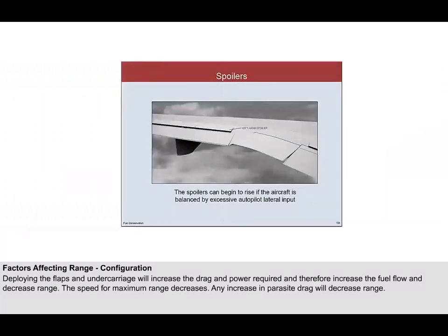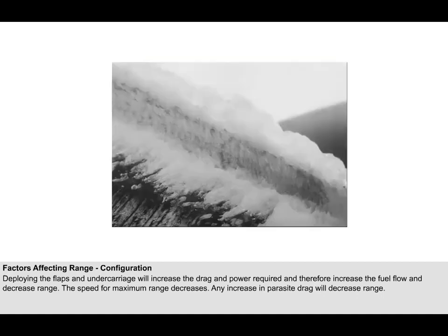An important point to consider over which the pilot has direct control is aeroplane trim. A pilot must periodically check the aileron and rudder trim, the spoilers, and the trailing edges to ensure that the aeroplane is in trim and is in balanced flight. Monitoring the aeroplane's control surfaces will help to reduce the extra drag and extra fuel consumption that out of trim and unbalanced flight can cause.